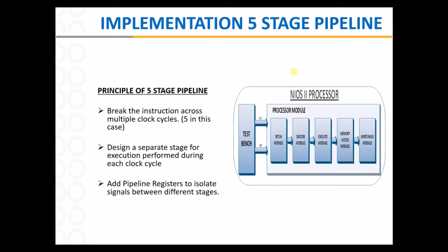Here, there are 5 stages: fetch, decode, execute, memory access, and write back, which have to be designed separately. Add the pipeline registers to isolate the signals between the different stages. This design gives a basic idea of the implementation of the 5-stage pipeline.